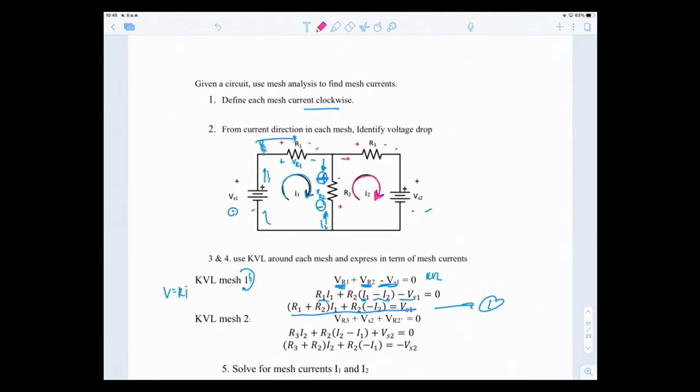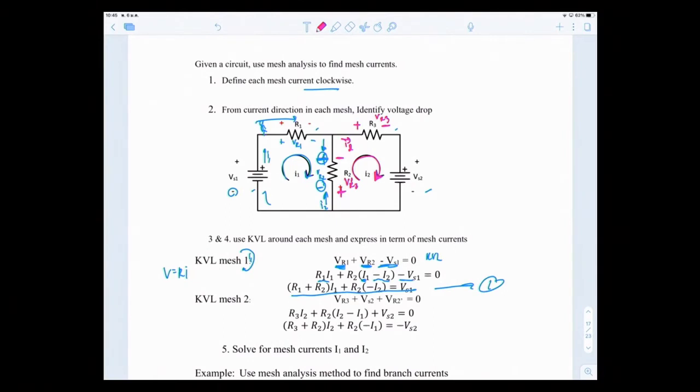Okay, so as I2 enters R3, you have positive, negative, right? VR3 comes here, and it would be positive, pink, we are pink now, minus, let's call it VR2 prime. So therefore, write KVL. If I start walking from here, going along with current I2, you see positive VR3, positive VS2, and then positive VR2 prime.